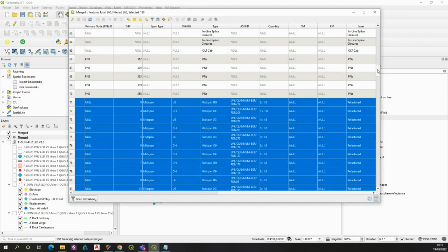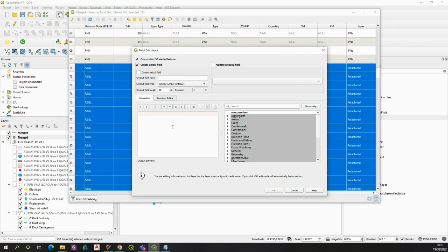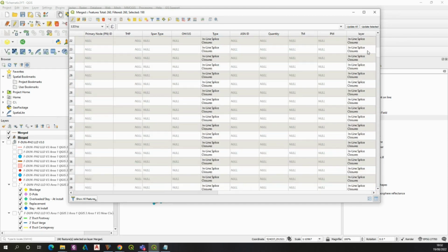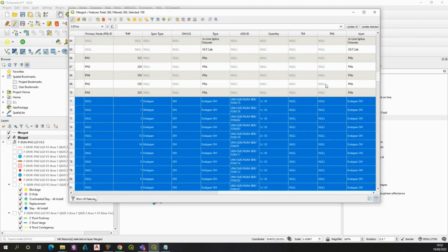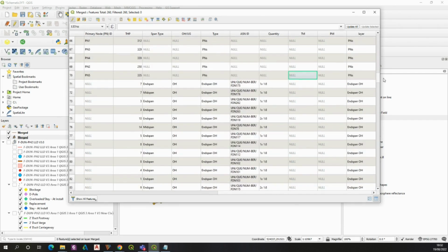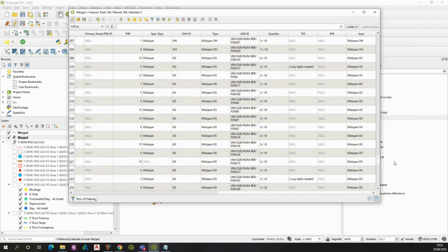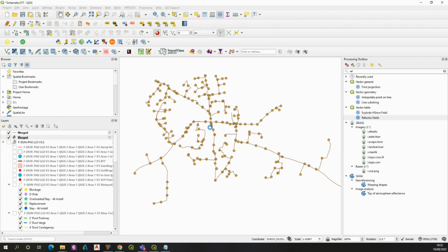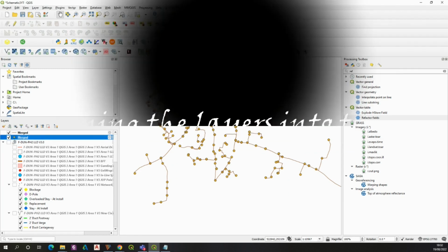Now I have the stuff selected, so by running the field calculator I can just press type and close it into the quote and choose the layer. My data from type will be transferred to the layer. Alright, so in this case I don't really need the type column, I just need the layer column, but I can keep it for now, just in case. Anyway, we'll work on the layer column in both cases. I hope that you understood everything until this point, because this situation completes another step with FTTX straight line diagram preparation.